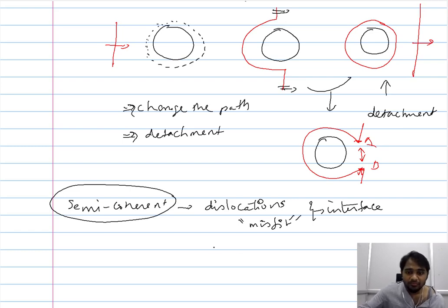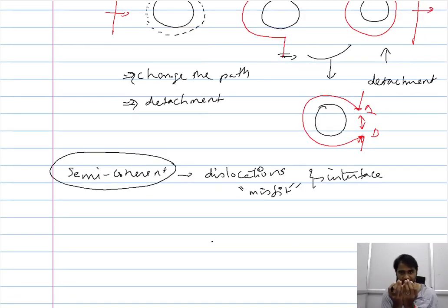So when the propagating dislocation meets with the semi-coherent atoms, there is an interaction between the already existing misfit dislocations and the propagating dislocation, and therefore this interaction impedes the rate at which the propagating dislocation moves. This is in addition to the other ways that the movement of the dislocation is impeded.